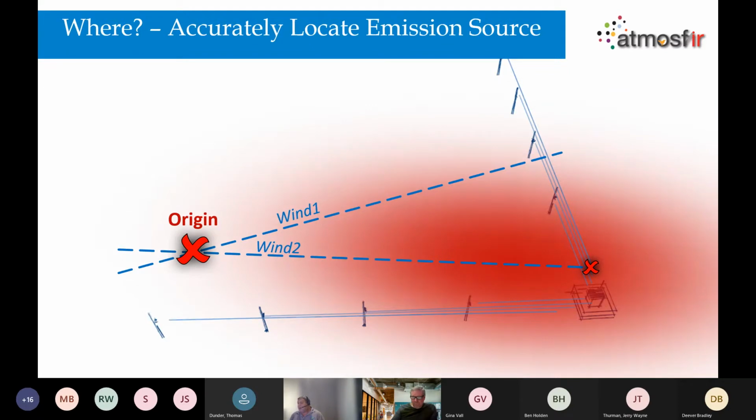We can easily tell you if it's coming from your facility or from your neighbor facility, but we will not tell you if it's coming from the specific flange. We can give you the area, let's say 50 meter by 50 meter or 100 meter by 100 meter, but this technology will not tell you what is the flange. For that, you will need to take your sniffer team or your LDAR team with OGI cameras or with a sniffer and find the leaking problem.